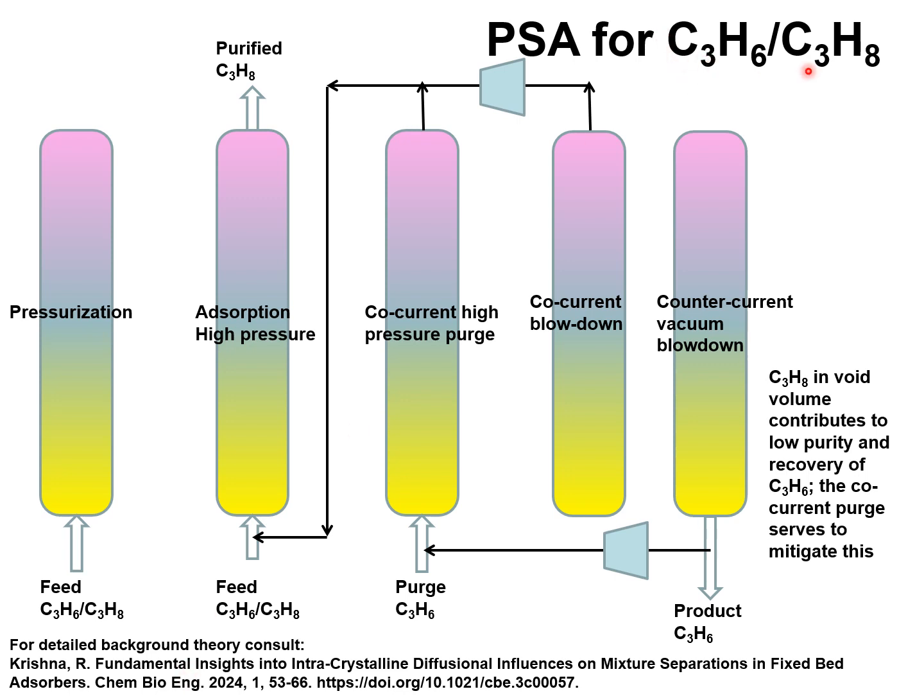The separation of propene-propane mixtures is important in the process industries, and for propene feedstocks to the polymerization reactor, the purity requirements are about 99.95%, which is currently achieved in distillation operations. There's considerable effort in the development of metal organic frameworks and zeolites for separations of propene-propane mixtures.